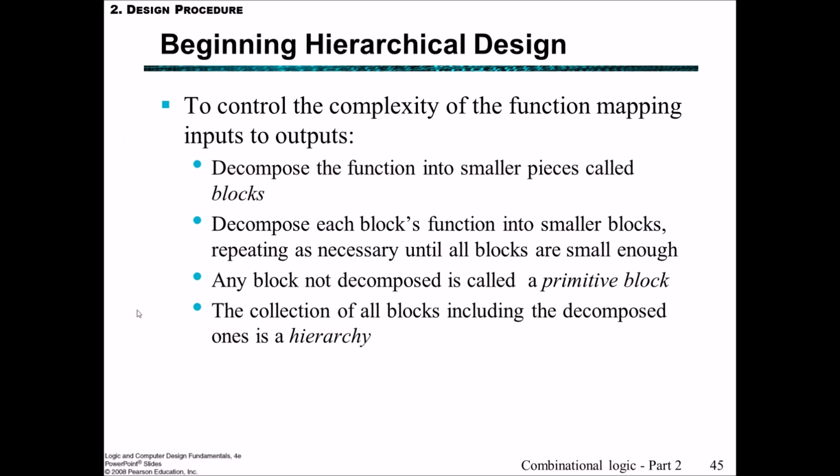After those previous examples, you've probably started to realize that the circuits can become quite complex when we're mapping the inputs to the outputs. Clearly then, it's advantageous for us to decompose those functions into smaller pieces, which we're going to call blocks. And this is really how hierarchical design starts. We're trying to decompose each of the blocks' functions into smaller and smaller blocks. And we just repeat that until all of the blocks are small enough to manage, small enough to understand. Any block that's not decomposed is called a primitive block, and the collection of all the blocks, including those decomposed ones, is the hierarchy.